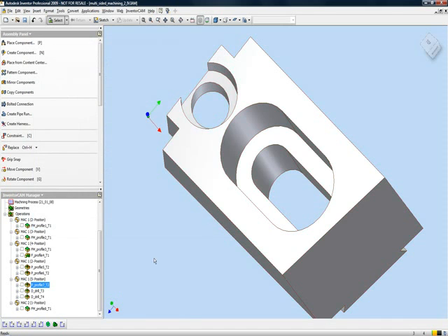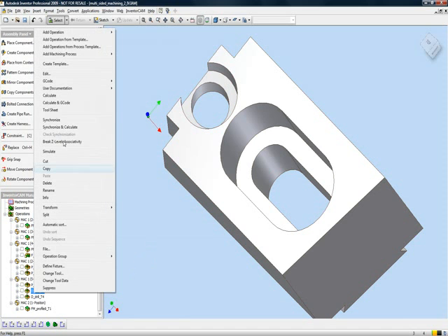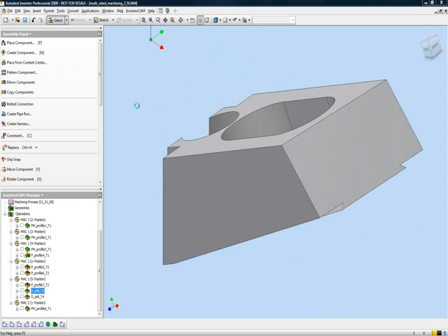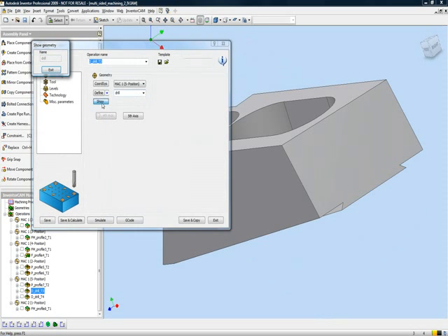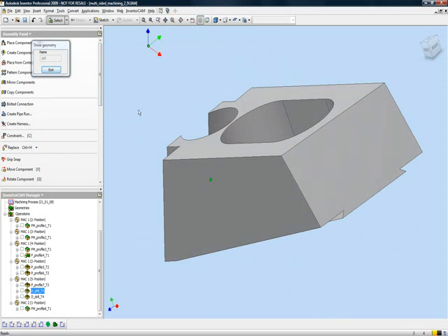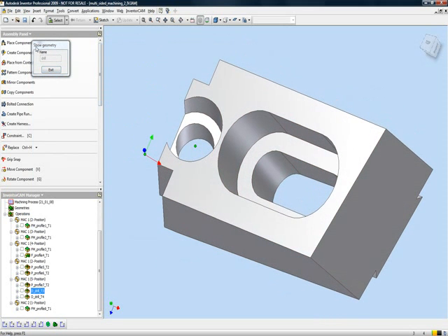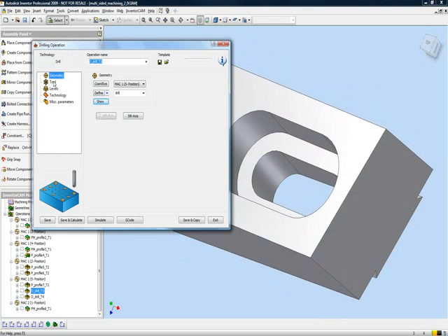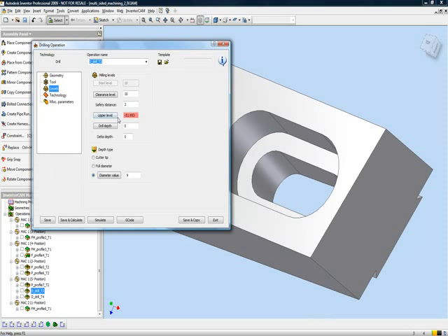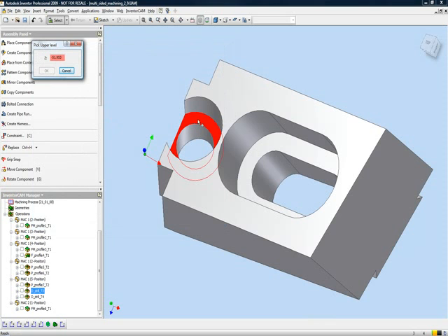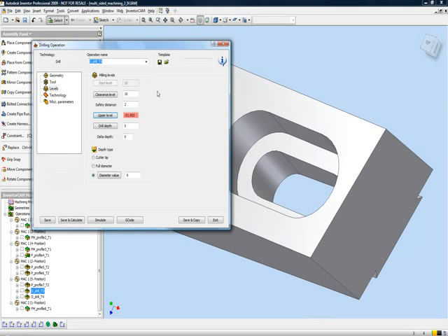In my following operations after that, I've done a drilling operation where my geometry, again using position 5, is the hole itself over there, as you can see, the center of that hole, using a 10 millimeter center drill, spot drill for this operation. My upper level being this step over here, the top of the floor, and my drill depth being at 0, but having the 9 millimeters of the tool get down to this level over here.